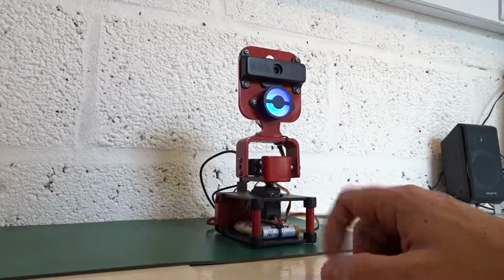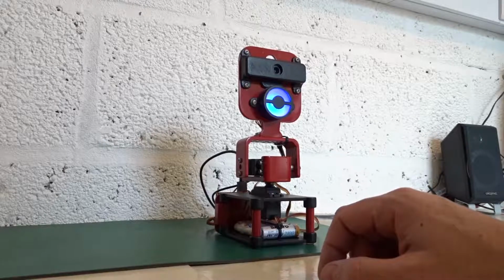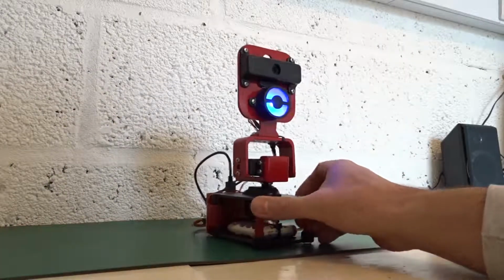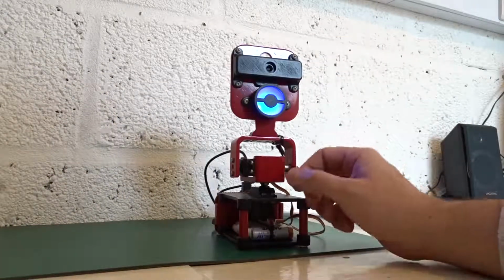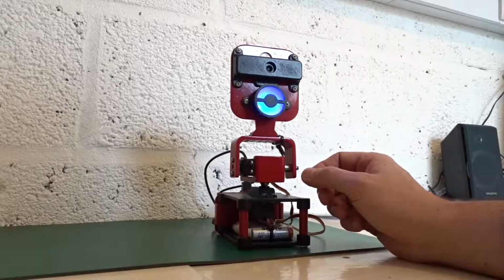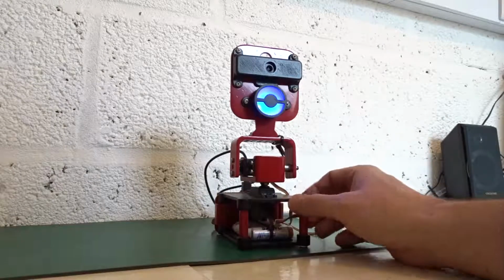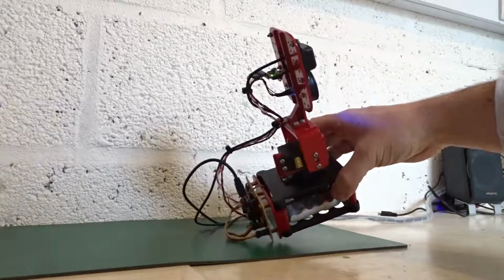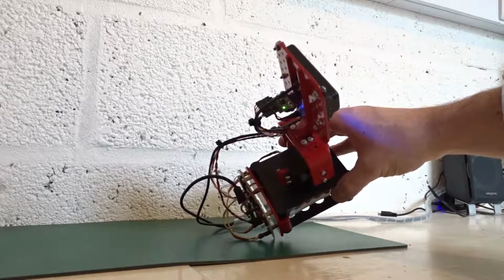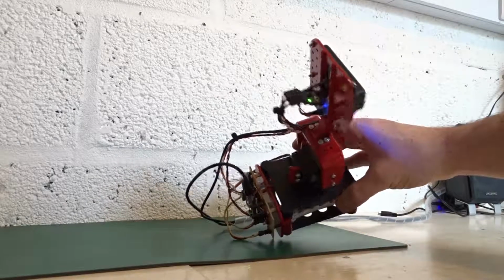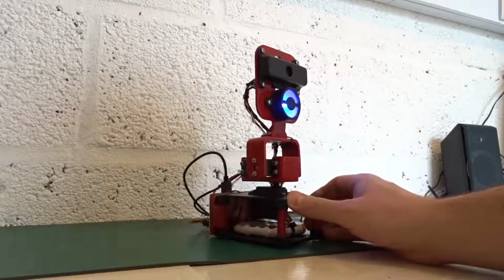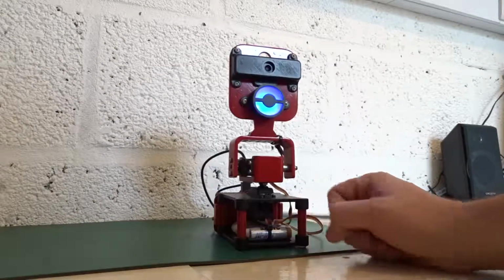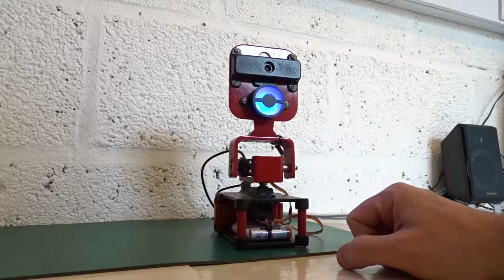Since the last video on my robot head build, I've made a few changes to the robot head. I think I discussed in one of the videos the fact that the sonar sensor was not overly reliable in this application, so I've made a few changes. The main one being removing the sonar sensor and replacing it instead with an accelerometer. It's an MPU 6050 accelerometer unit, and from it I can get roll, pitch and yaw values.